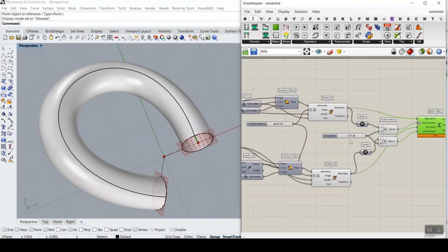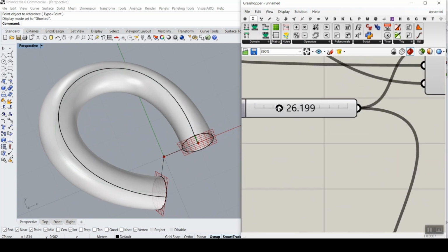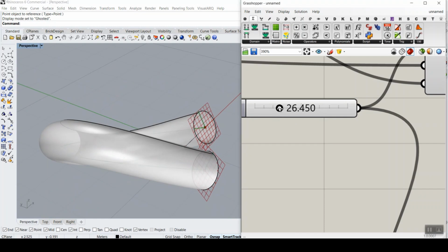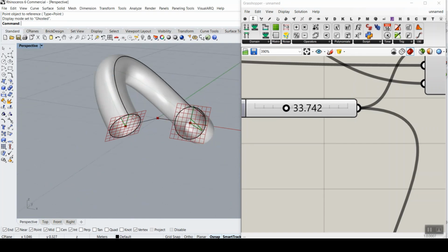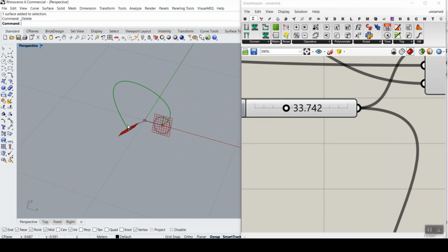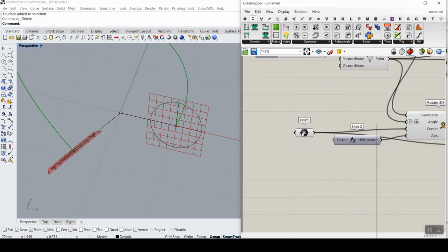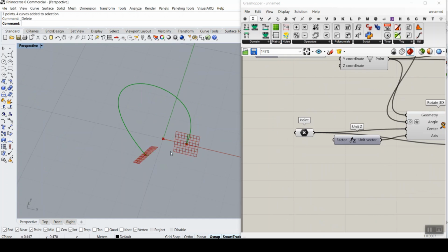But remember, you have to also play with this rotation. Remember that this is also the rotation here, and you can see that we can have that. Okay, that's how we can actually make it in Grasshopper. To the center of this point, I'm going to internalize that. Right click and internalize, so I can just get rid of everything and check it out.